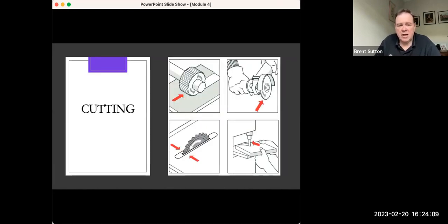Cutting, it's the old classic. Once again, even if I look at a skill saw as a good example, or a table saw, think about that adjustable guard, if you're cutting, say, a material of more than 6 millimeters in thickness, as that adjustable guard or self-closing guard opens as the material goes through, the fact is that gap is sufficient for a finger to enter the zone. So just because it's got a guard, you need to check that people can't be exposed to that cutting hazard.